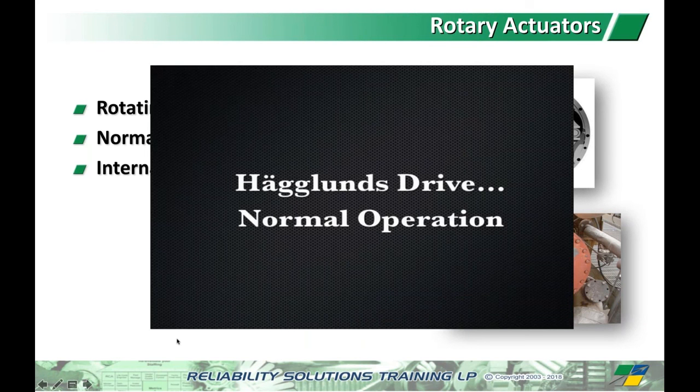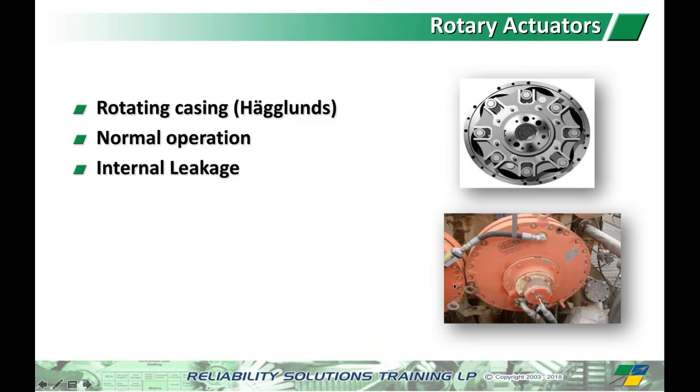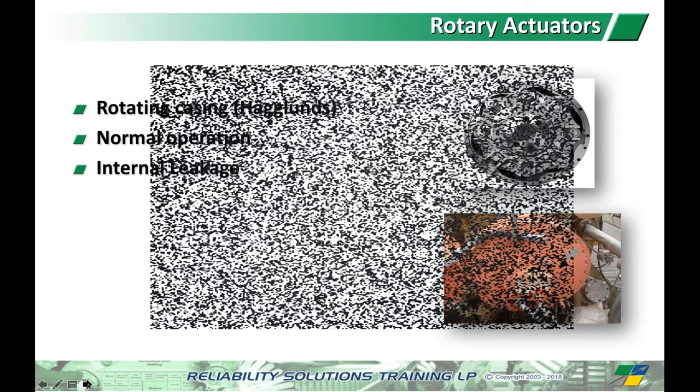We went in with ultrasound and started listening. And really, I'm just probing around on the casing here, somewhere on the axial right here is not a bad place to be, out on the periphery. So you're sort of out in this region out here, which is where the leakage would be occurring. And here's what we got.